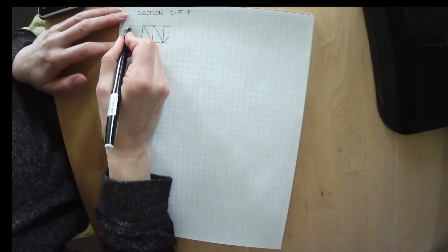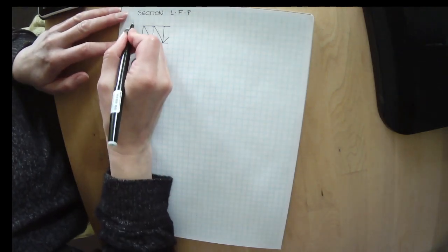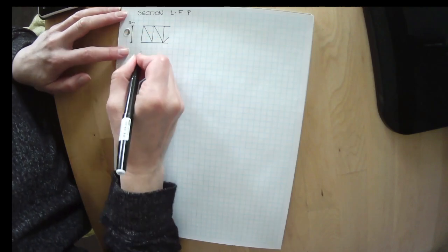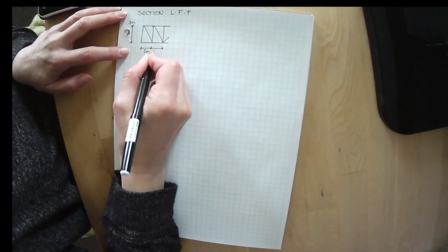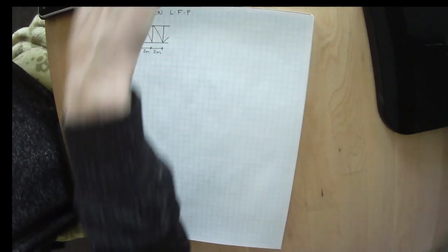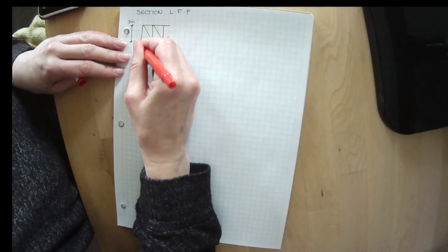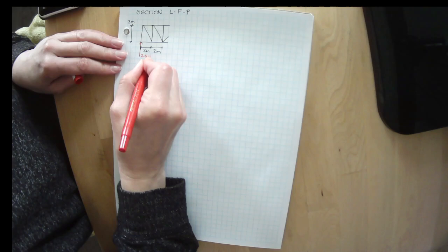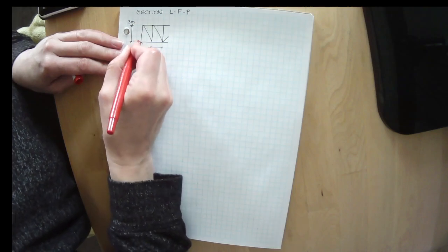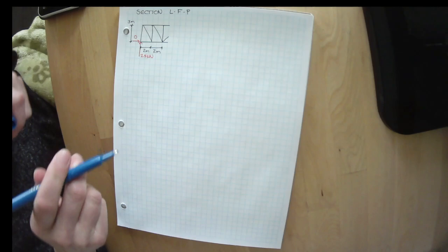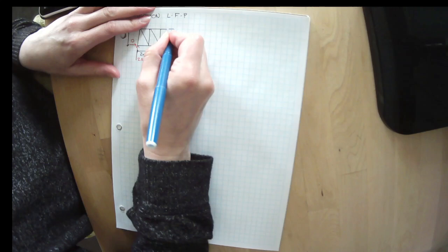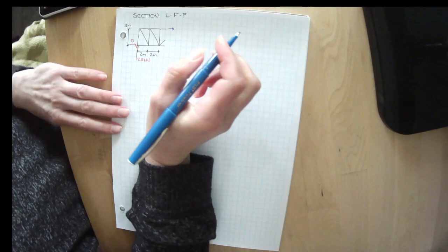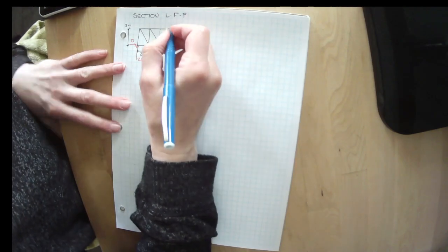So we know that this is 3 meters, and we know that that's 2 meters, and that's 2 meters. We know that there is a reaction here of 25 kilonewtons, and that is 0. And then we have unknown internal forces here that I am going to draw in the positive direction, or in the tensile direction, not in the positive direction. I'm going to draw them in tension.